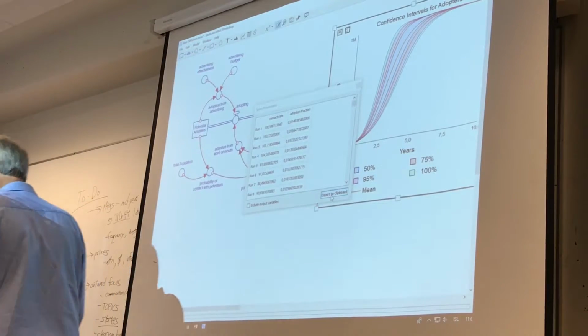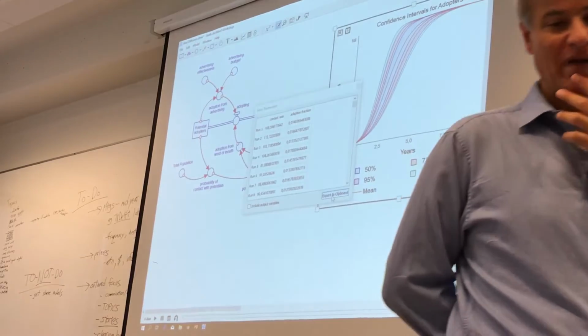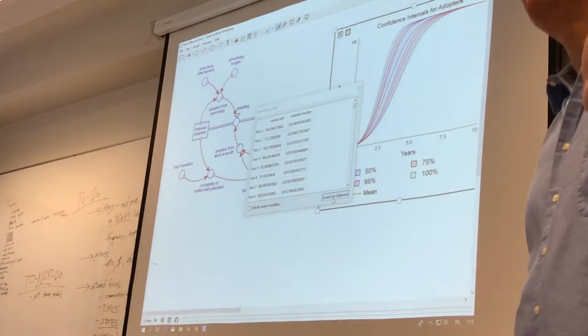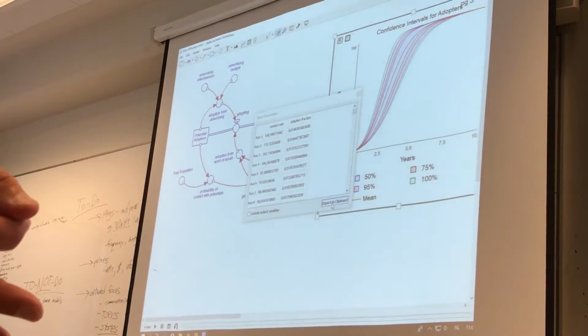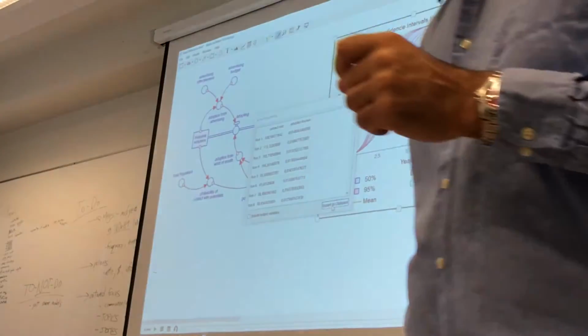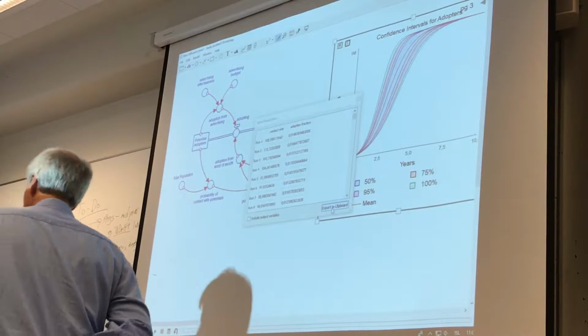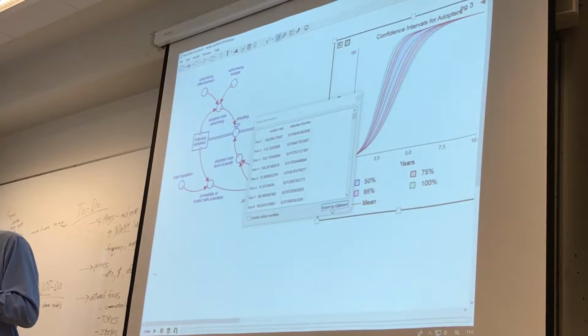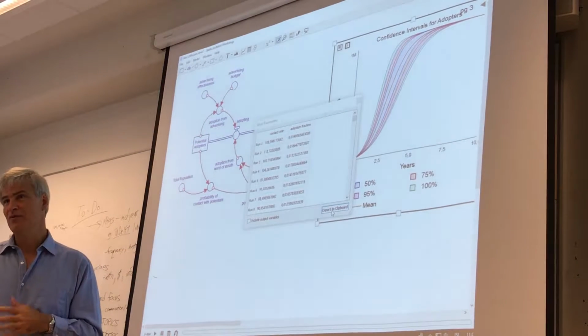We have a blog article on that, and also something in our documentation. Basically, we default to a DT of 0.25, and that works great across a broad range of problems. But your DT has to be less than half of your smallest time delays. They're usually parameters, but you may not even know what that is. If you do know, you just cut it in half or in a quarter. If you don't know, start with 0.25, it's fine.